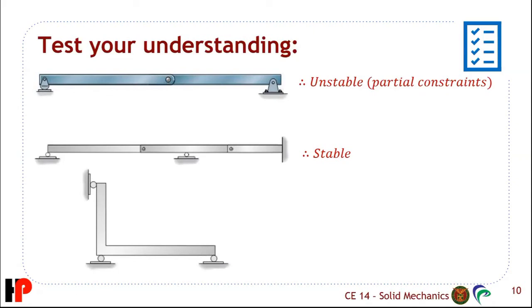So this beam is stable. That is because all support reactions are not concurrent nor are they parallel. So ito horizontal, vertical. So this beam, although it looks unstable, it is stable because remember, roller support also provides support reaction either to the right or to the left kapag ganyan, or dito up or down.